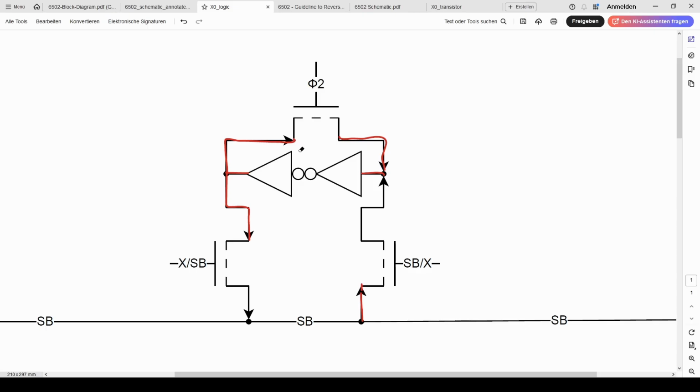In fact, that appears to be the reason why the 6502, the original one anyways, would lose register contents if it were halted for too long, because eventually this electricity would still dissipate, and so it can only hold this high for so long, for approximately half a clock cycle, maybe a bit longer, and so it needs to be constantly re-enabled.